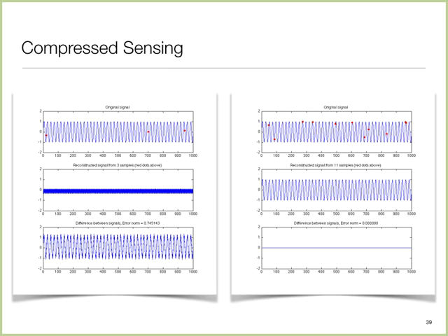One is that we know more about the signal, and therefore we could be smarter about acquiring the information. In Shannon-Nyquist, we basically assume that the only thing we know is the bandwidth, whereas if we know more, and the example I had was, what if we knew it was a sine wave, then we know a sine wave only needs 3 parameters, so I could start from that.